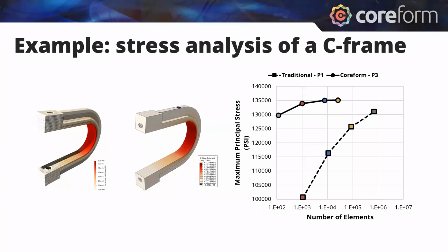And then alternatively, if instead the question is now we're going to solve these with iterative solvers, and now I've only solved something like 1e minus 3 or 1e minus 5, is that uncertain or not? And I guess my answer there is that in many cases we don't even know our material properties to an accuracy of 1e minus 5 from a relative or scientific accuracy standpoint.